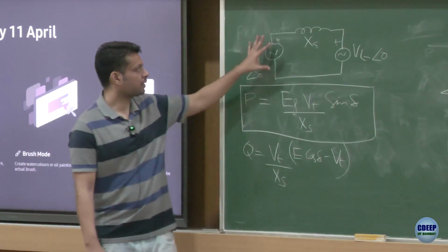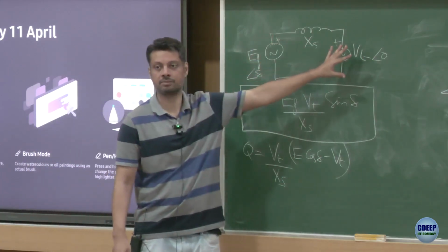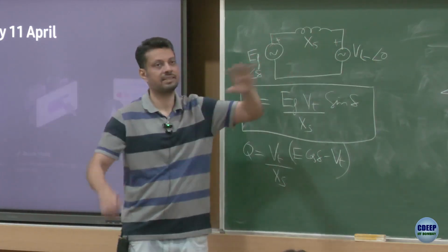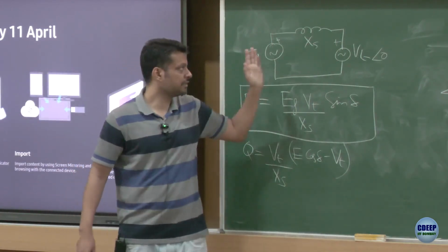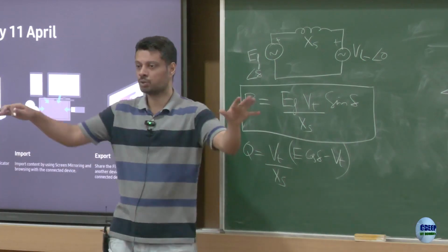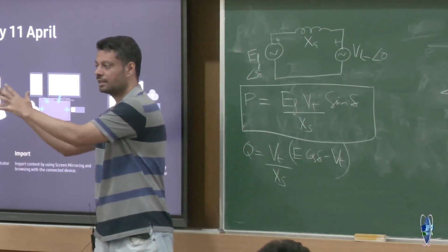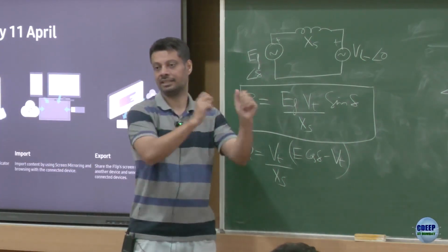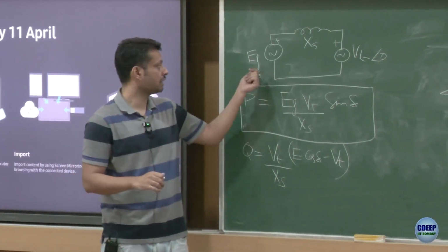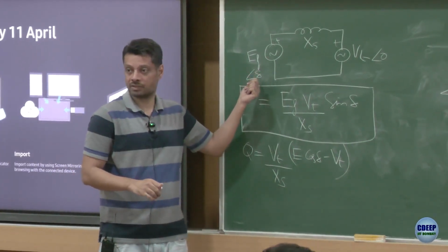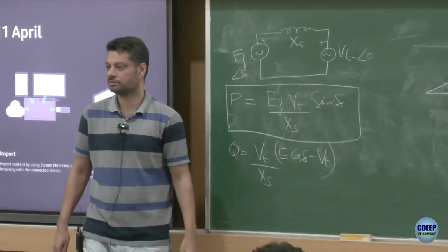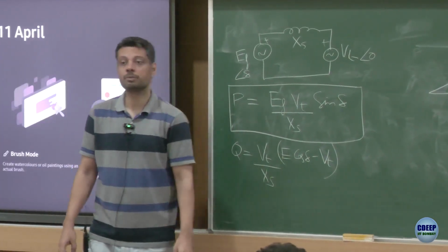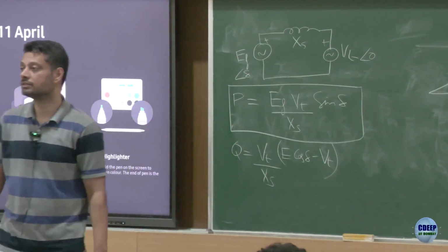Let us say these are two big generators running far apart, there is a line which is interconnecting them, and they have their local loads also, right. I want to transfer 100 kilowatt from this generator and load or this city to this city. What should I do? Somehow I should try to lead this voltage by a certain angle which corresponds to that much of power transfer. Is that okay? Not okay? Does anyone want me to repeat this sentence?